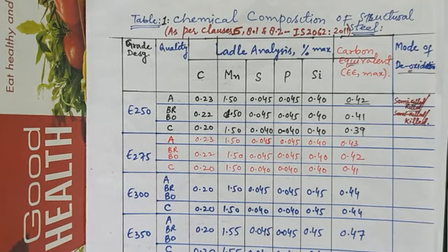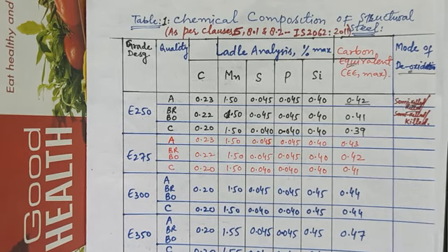Now during the iron or steel making process, the hot metal contains very high levels of carbon, about 4%, and other impurities as well. So steel at this stage is very brittle and is not suitable for structural purposes. This hot material is charged to the basic oxygen furnace, where oxygen is blown into the liquid metal in a controlled manner, and the carbon content is brought down to 0.1 to 0.25%.